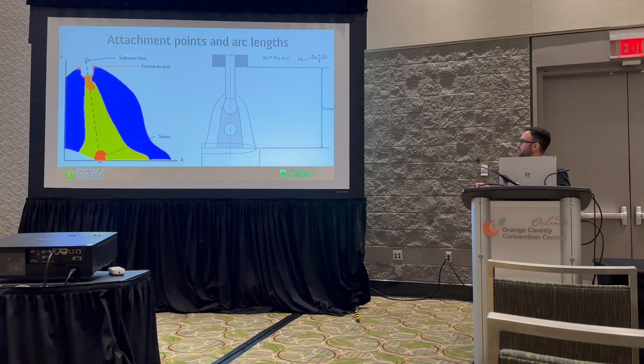So here we have the external arc. Again, we're finding the maximum points from the two regions. If we take the average, we find the characteristic distance, the arc length distance for the shielding arc region. If we repeat the process for the multi-consumable, at the top of the orange here, we will obtain that respective characteristic distance, and if we recall back to the contact tip to workpiece distance, the difference between those two will simply be the length of the electrode extension.